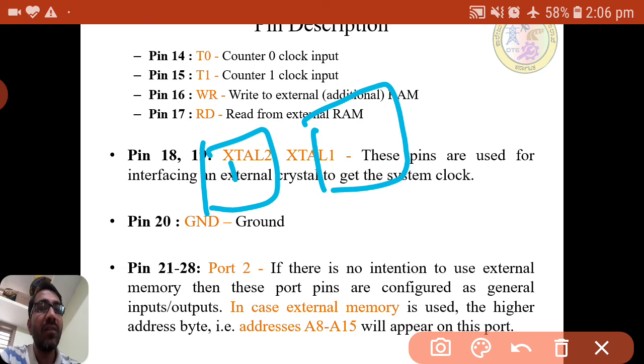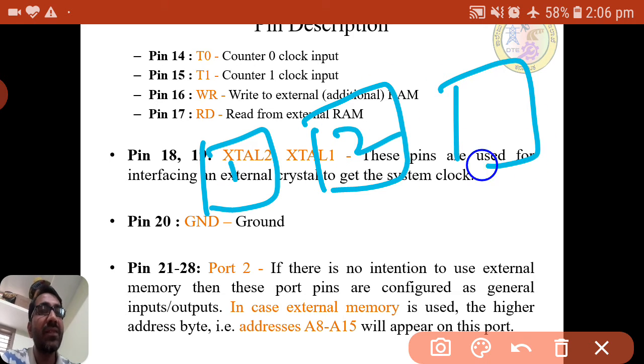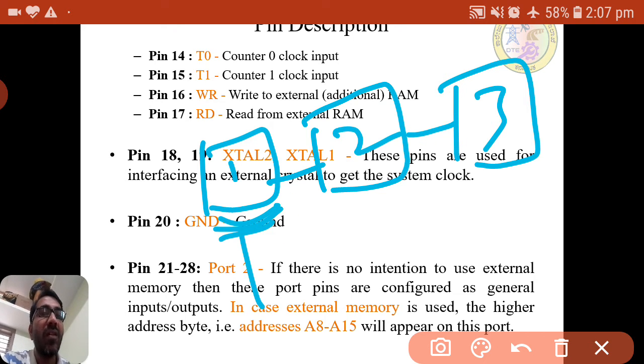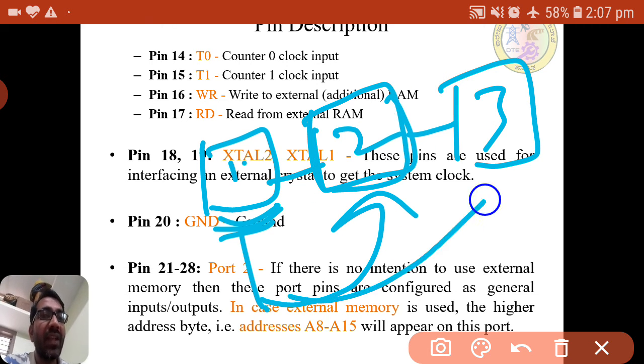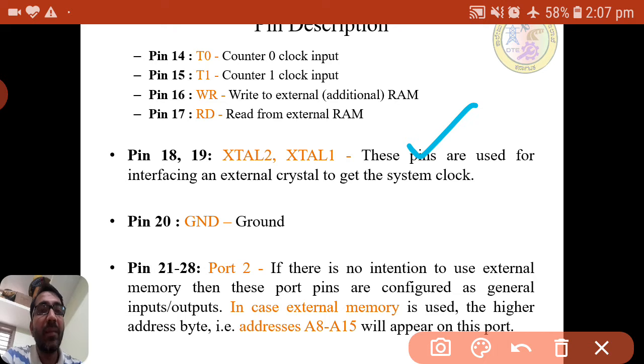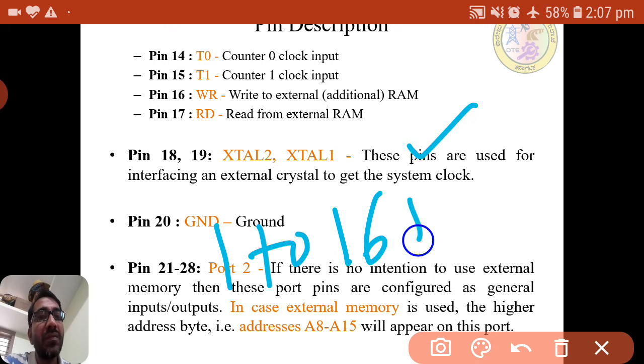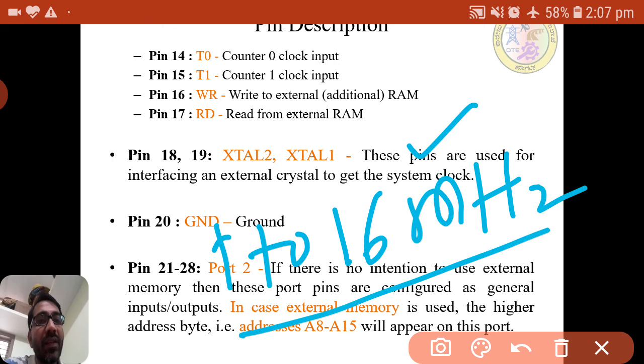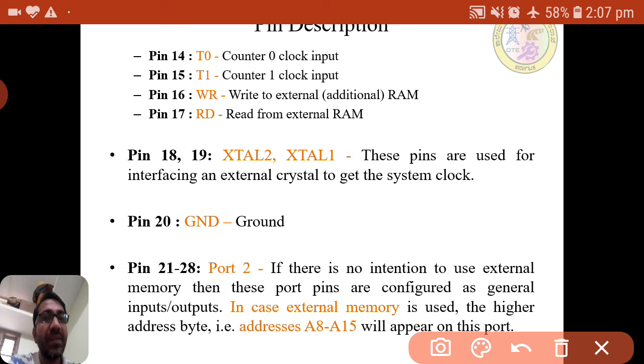First this work is performed, then this function, then this function, like this. All these things have particular times, so that after executing one device, the next should work. All of this is controlled by the clock, and the microcontroller will work from 1 megahertz to 16 megahertz. Usually 12 megahertz is the most common frequency used, and it is generated using the XTAL pins and a crystal oscillator.